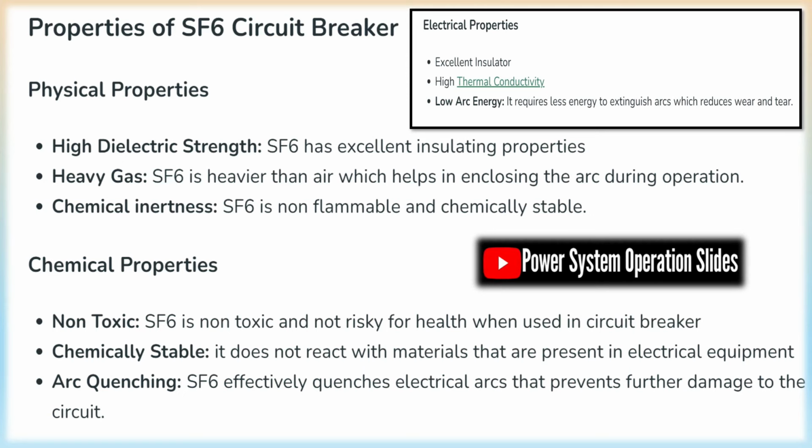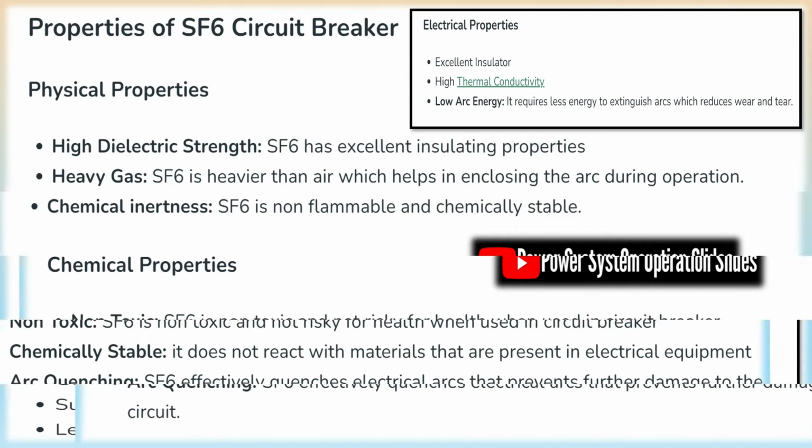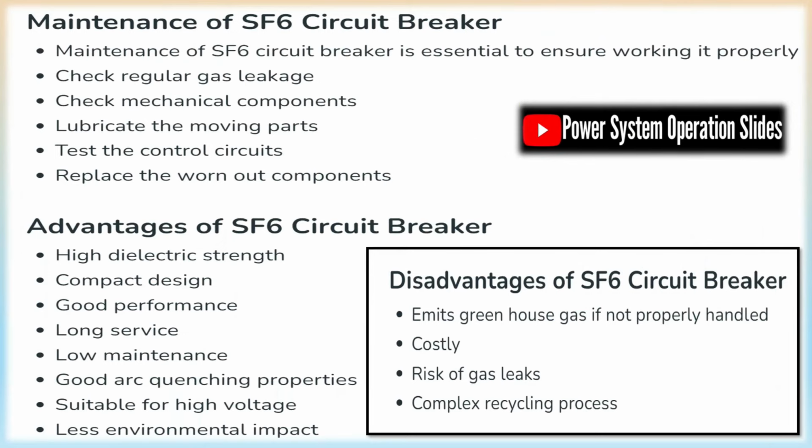Just like any other insulator, it provides adequate line-to-ground dry arcing and creepage distance to prevent flashovers associated with transient overvoltages and ambient pollution. The complete circuit breaker unit is usually fixed on a steel structure which secures it to an embedded concrete foundation.